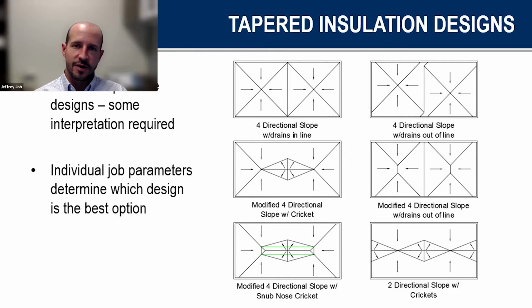So, for example, if it's certainly a large roof, maybe you have skylights, lots of penetrations for whatever reason, mechanical systems, etc. The tapered system can be laid out really based on any geometry of the roof, what the shape of the roof is, penetrations, where your drains are, scuppers.